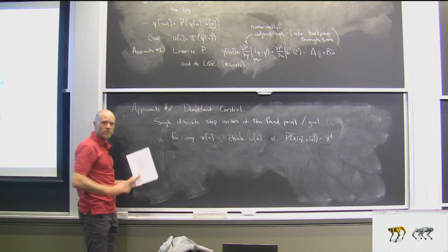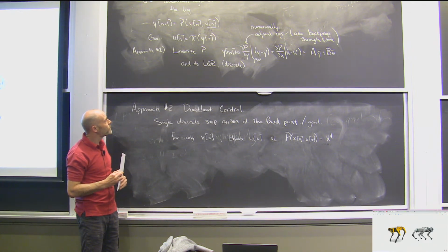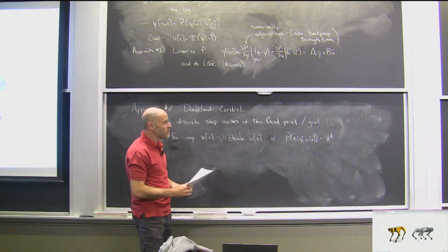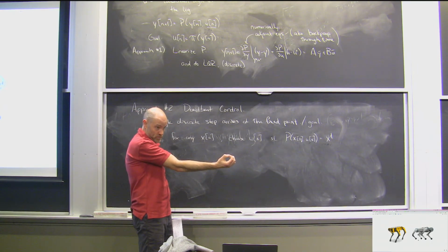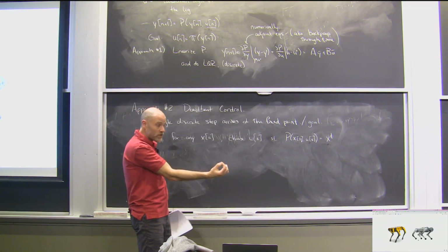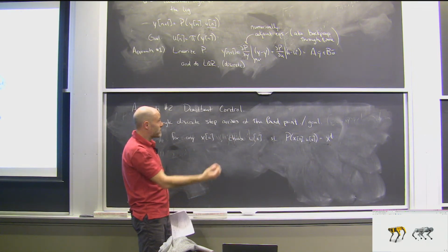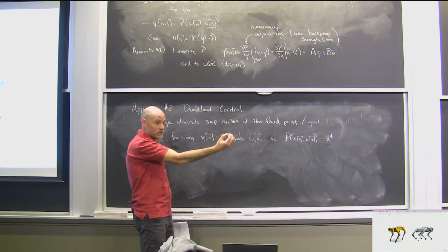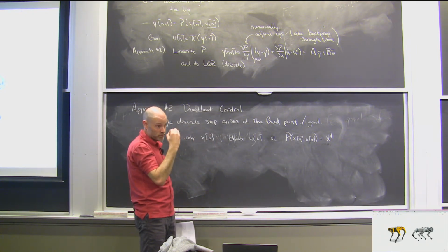Okay, does that make sense? Yes, sorry. Maybe a bit of a story. What's the point we're linearizing around in the LQR approach? Yep. It depends what your control task is, but if you want to just stabilize, like increase the rate of convergence to the nominal limit cycle, that would be fine. You could potentially also try to stabilize a point that wasn't originally a fixed point on the Poincare map. So you could imagine it as being a desired hopping height. You could linearize around that and turn an unstable hopping height into a stable one. Yeah, so y star would be your desired height.